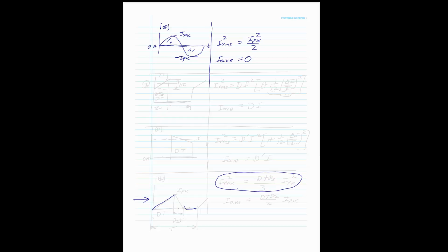The next common waveform that we see is the regular waveform with this ramp coming up, the inductor ramp. And that's during DT, and we see that in the buck converters. And then it repeats, and so on. But this is the period T again.